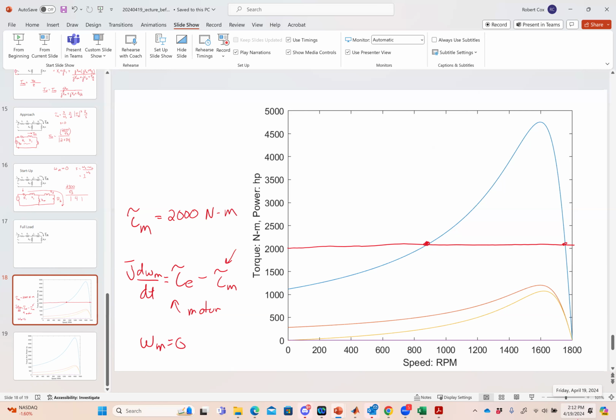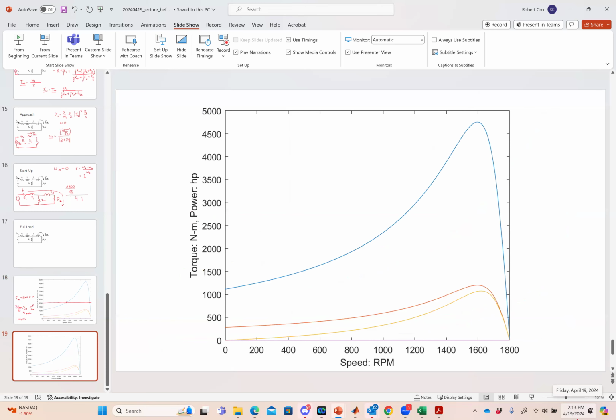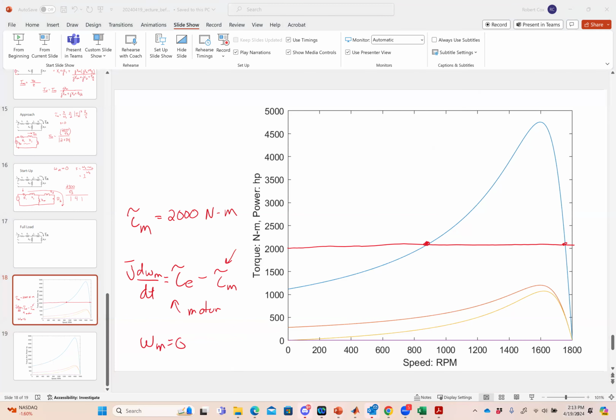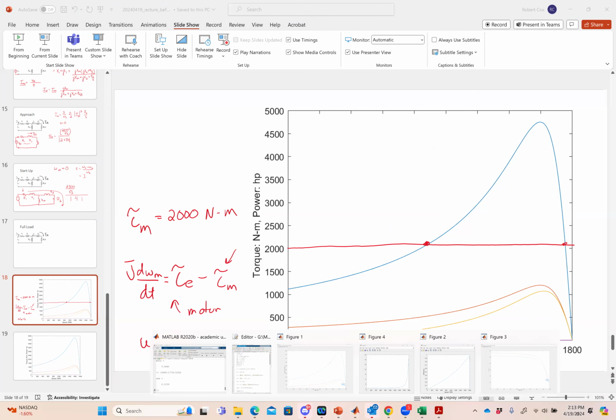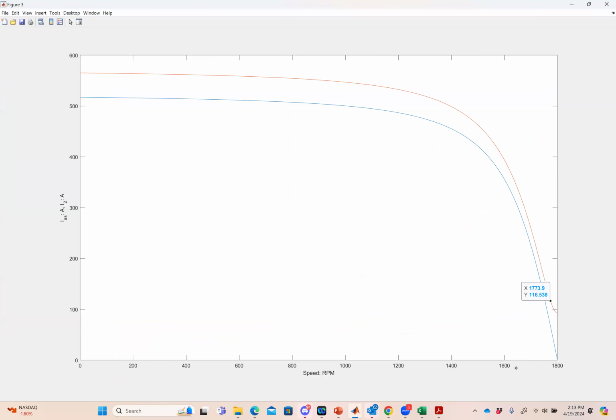These are going to be imbalanced, but the important thing is physically, this machine is going to try to make as much torque as it can. Essentially, it's going to be stuck in a stall condition. And what's true about its current? Its current is going to be incredibly large, and it's stuck there. So it's going to be incredibly large until what happens? Until it blows up or the protection kicks in, right?